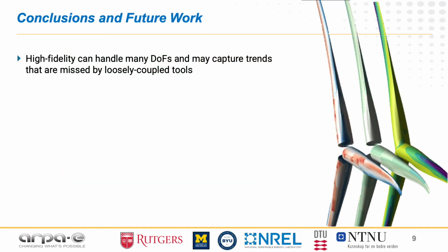In conclusion, in this project, we showed that using high-fidelity computational tools for the optimization of wind turbines offers a robust and automated way to explore their large design space. Additionally, high-fidelity optimization may also lead to optimal solutions that better exploit interactions between the engineering disciplines involved. It's quite obvious that having to run CFD within the optimization loop leads to significant computational expenses.